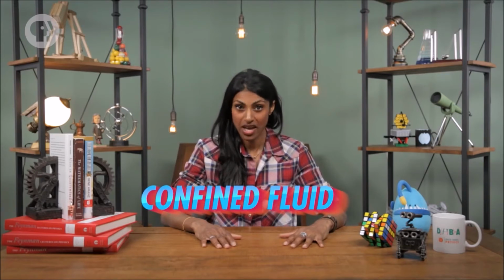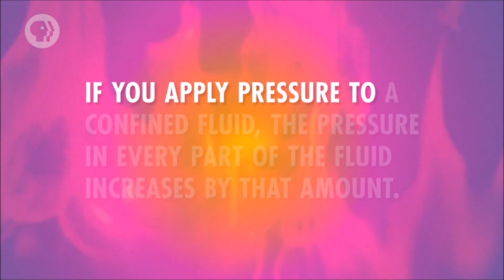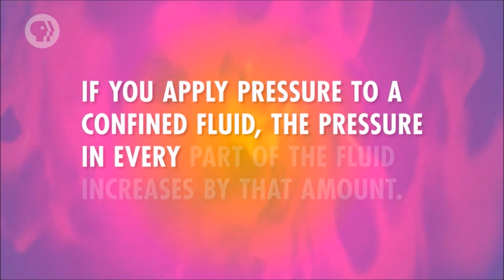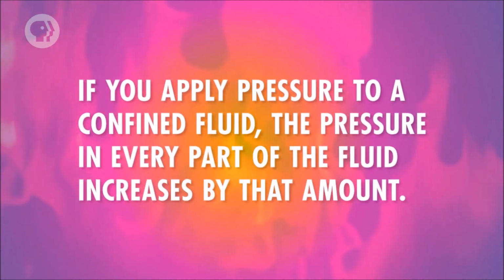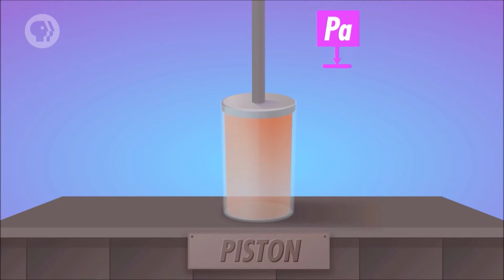The water in the pool could be one example of a confined fluid, because if you had a piston the size of the pool's surface and used it to push down, the water would have nowhere to go. And back in the mid-1600s, French physicist Blaise Pascal realised something about the way pressure worked in confined fluids. If you apply pressure to a confined fluid, the pressure in every part of the fluid increases by that amount. If you have water in a cup and you use a piston to apply 10,000 pascals of pressure to the surface of the water, then the pressure everywhere in the water increases by 10,000 pascals.